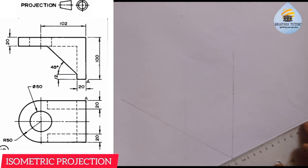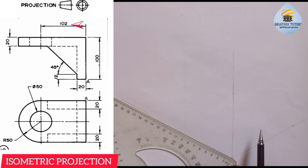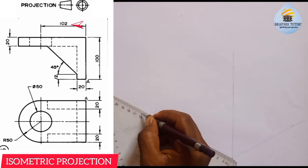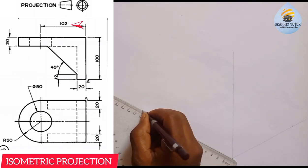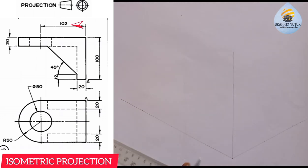So from 0 here to here is another 100. Hope you can see that. Then the length will be 102 plus the radius of this circle here, which is 50, and that will give us 152. So I'm going to measure 152. I can easily start from 1 here, and I'll measure 152, so from 1 to this point here. Since I'm starting from 1, I'm stopping at 16. If I start from 0, I'll stop at 15.2. So this is what we have here.